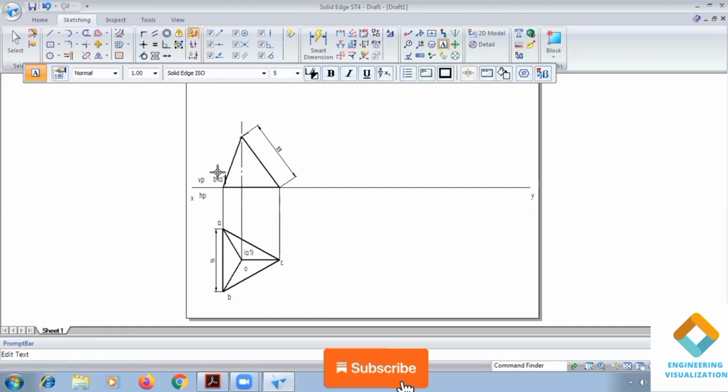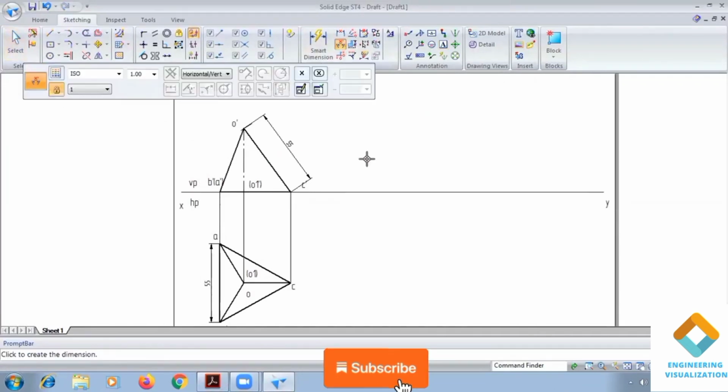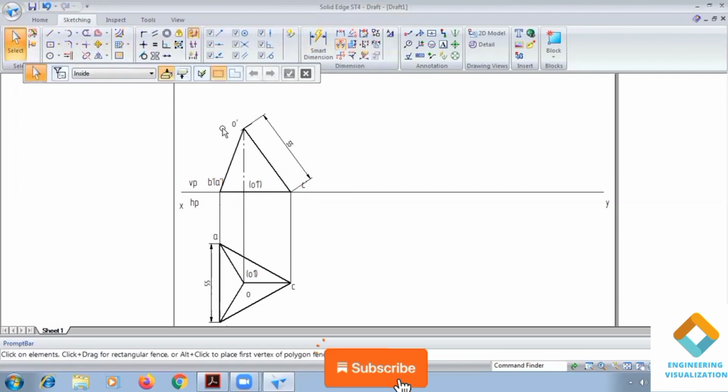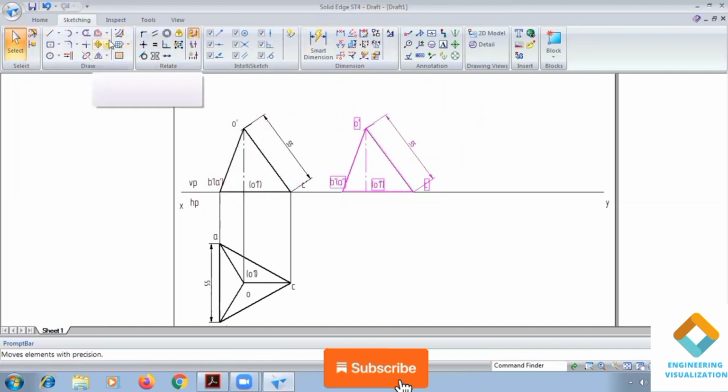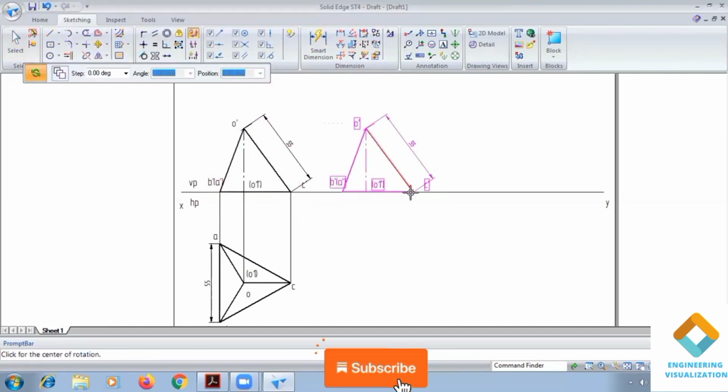So we are writing the front view notations: B dash visible, A dash not visible, O1 dash and O dash. Okay, next, the second position is nothing but the inclination with the base edge. Now we'll select this front view and go to the move command. Here we are rotating, so we need to copy along the xy line and then rotate and give the angle. So for this base edge, the angle is 50 degrees.